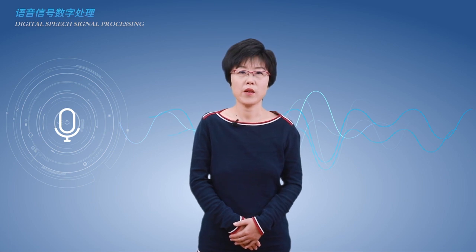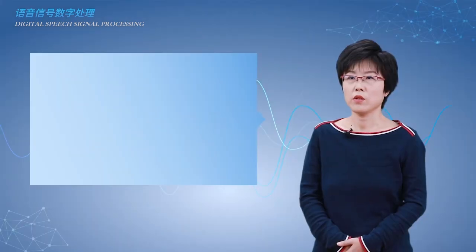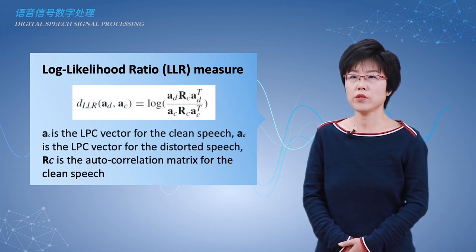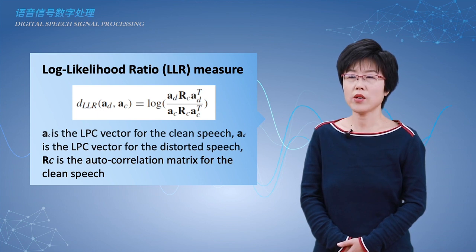It is well known that the speech production process can be modeled efficiently with a linear prediction (LP) model. There are a number of objective measures that use the distance between two sets of linear prediction coefficients (LPC), calculated on the original and the distorted speech. The log likelihood ratio (LLR) measure is a distance measure that can be directly calculated from the LPC vector of the clean and distorted speech.